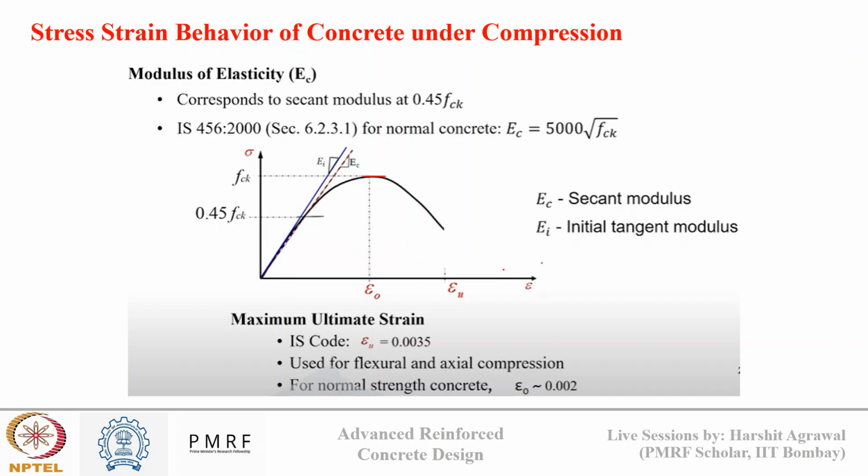However, for concrete in tension, there is only a small strength gain and then a sudden rupture. So we take 10% of the concrete strength as tensile strength, and we calculate the strain for that strength. After that strength value, we assume that concrete will no more take any load.